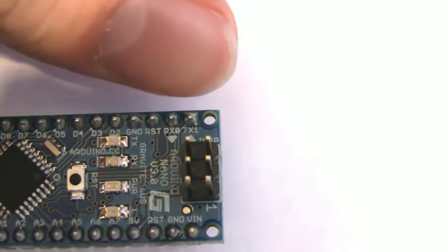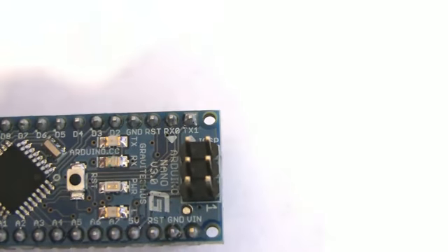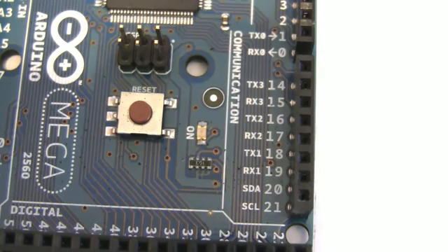Here you can see the TX and RX pins on the Nano. The Mega is a different story. You'll see that there's still TX and RX on pins 0 and 1, but there's also 3 more serial interfaces that you can use for communicating either with other Arduinos or just any other device that accepts serial communication. This comes in useful later on if you want to be able to simultaneously program the device and have it plugged into a separate serial interface.